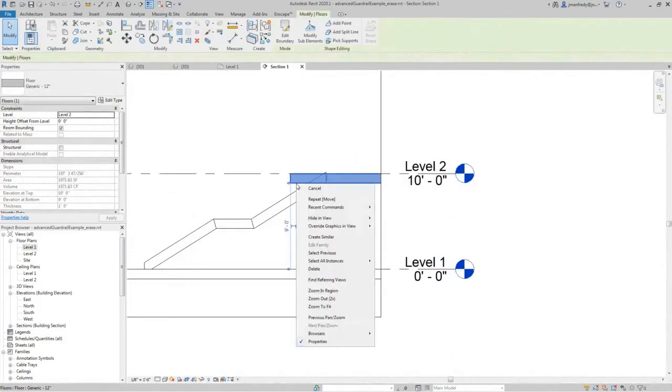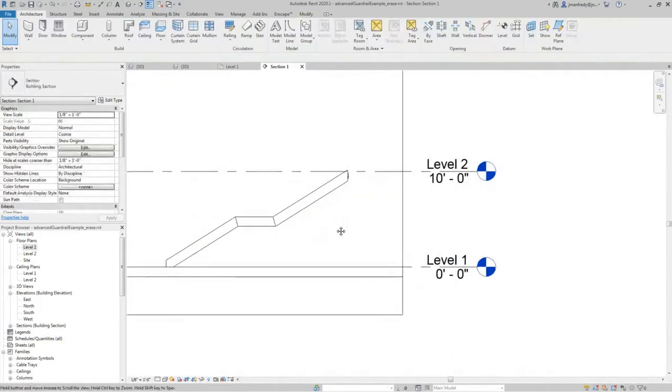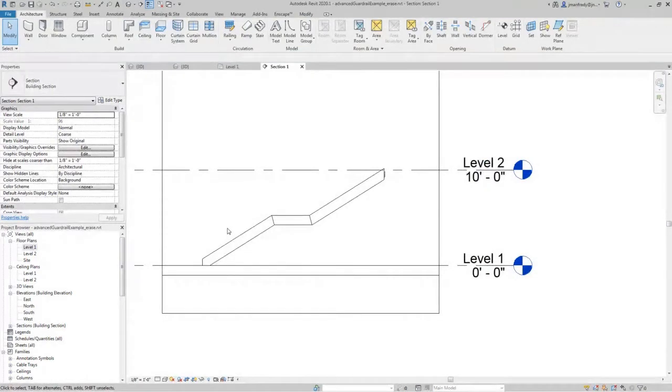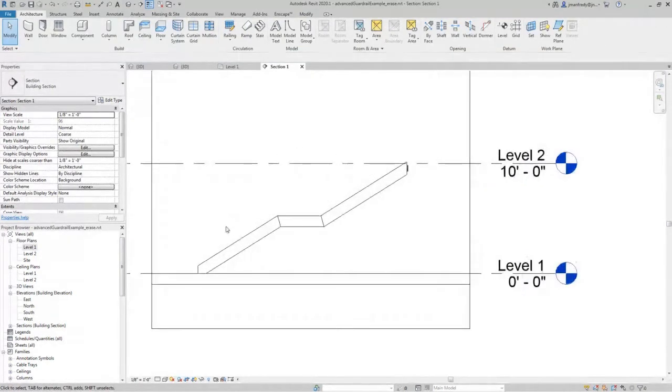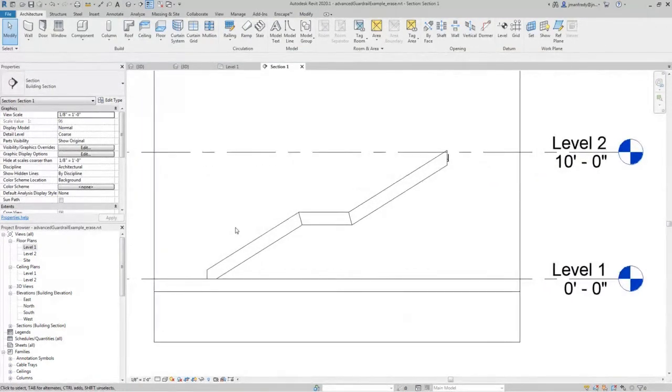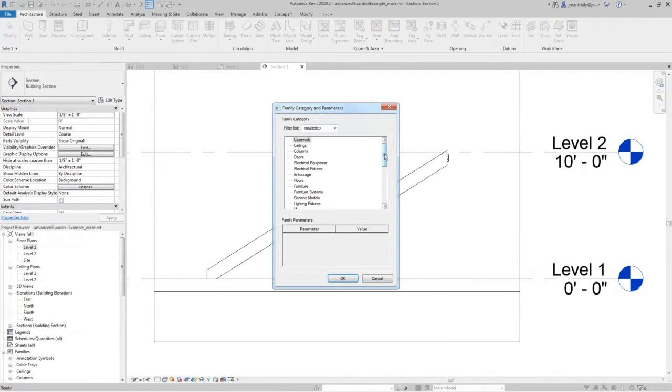Then what I do is I switch gears and I go to elevation view, and let me hide this floor for a second. Hide element. I'm going to tell it to draw my railing in elevation. So I'm going to sketch it out here. I'm going to go to component, model in place, and because I'm drawing a railing, I'm going to choose the railing family or the category here. So when I hide railings, this thing I'm drawing will disappear also.